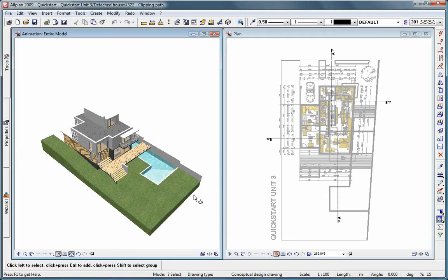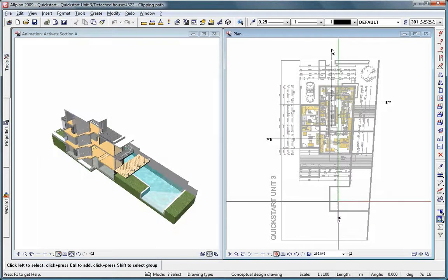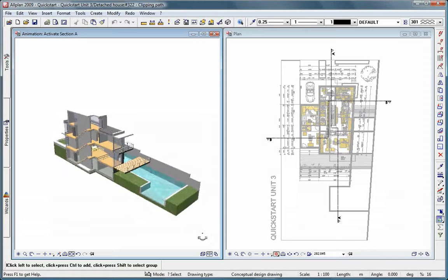As you can see here, 2 clipping lines have been added. In order to view a section, there are different possibilities. I can click on the section symbol down here at the right and can then enter the desired section name in the dialog line to open the section. Alternatively, I can also click on the clipping line in the floor plan. The section is automatically generated and displayed.